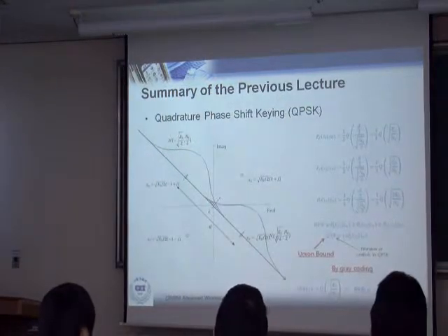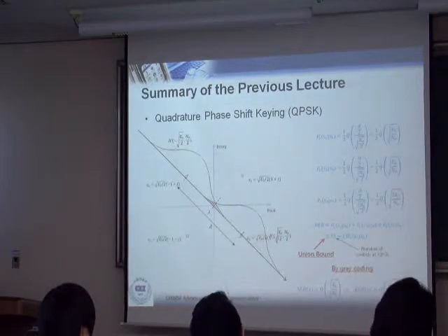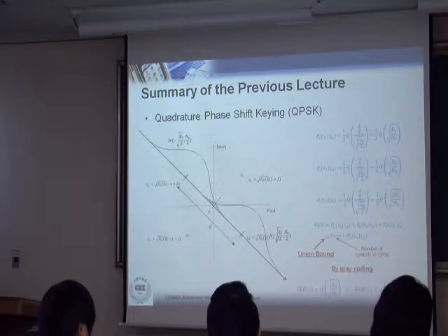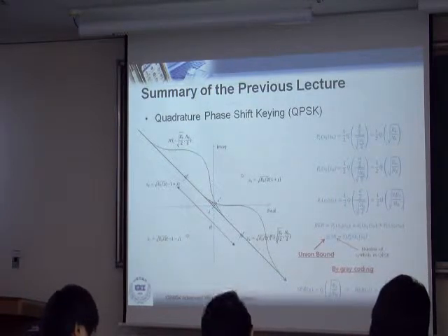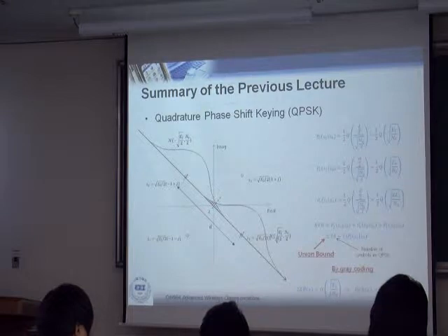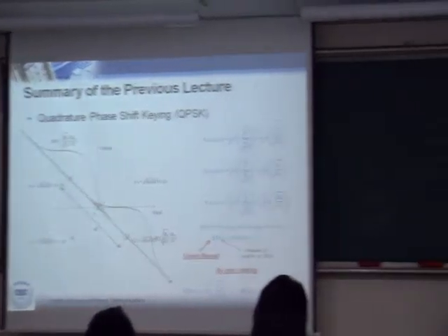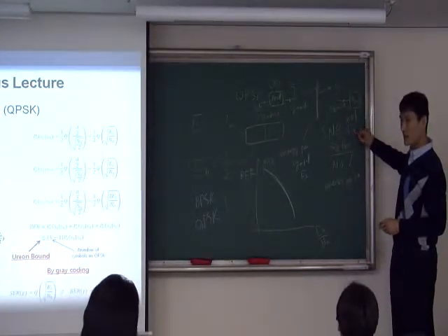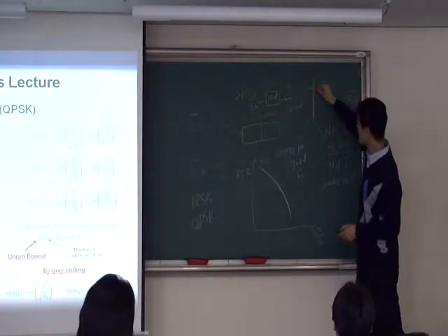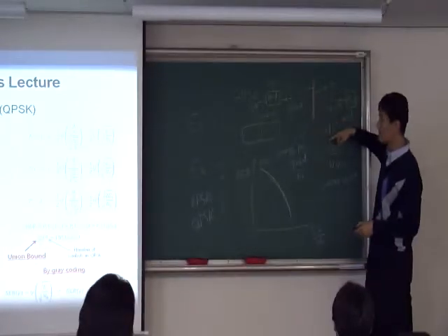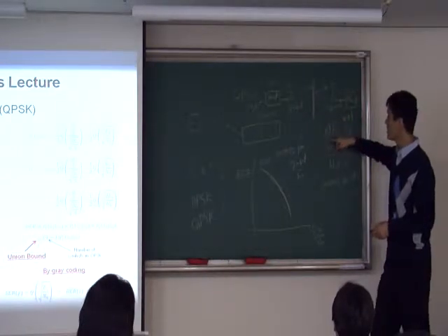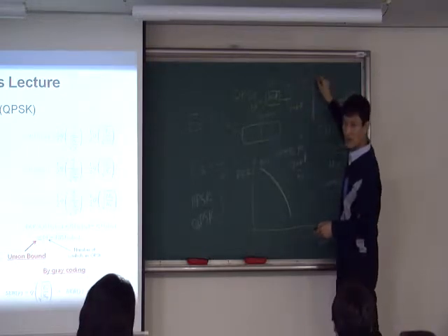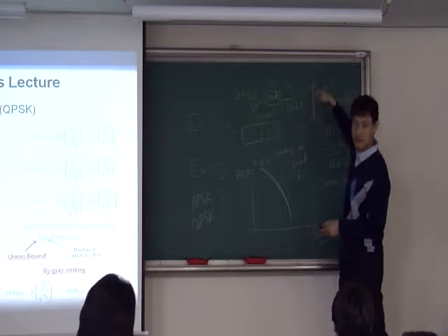So if you look at the BER, these two are the same. Think about this: Eb is fixed. However, that actually gives us a little bit of confusion, right? How come these two have the same error rate? The trick is that we fix the Eb. That basically means that if you cut it here in the channel SNR, in the QPSK case you are using a double channel SNR.